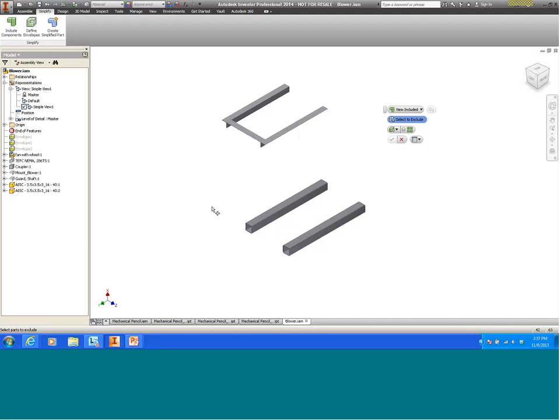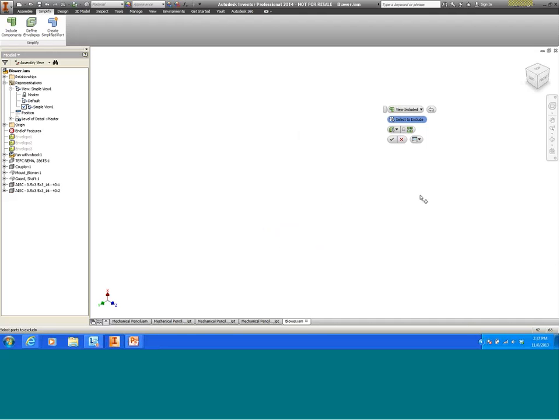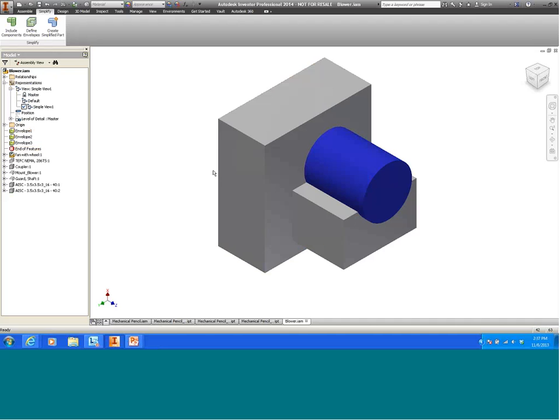And they're not showing right now simply because I have those assembly features suppressed. So I'm going to select to exclude. So I've excluded them all. I'm not seeing anything right now simply because I have those envelopes suppressed. I'm going to select OK, and I'm going to drag that end of features back so I can see those envelopes again, so you can see all 3 of them. So it makes it a little bit easier to see.